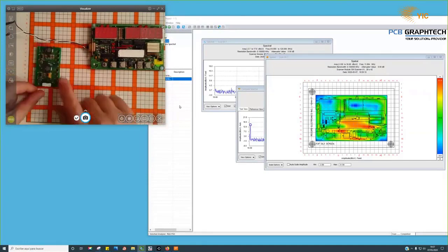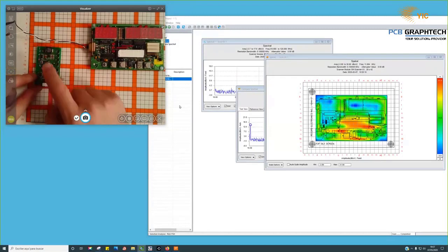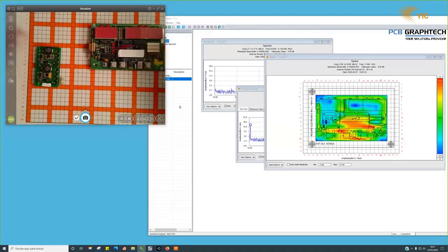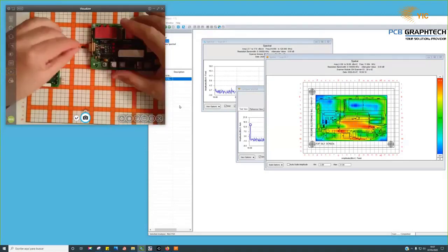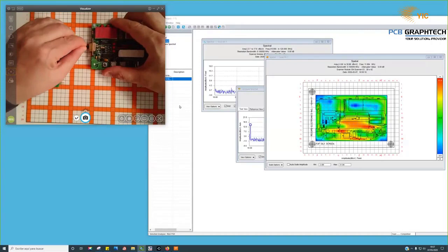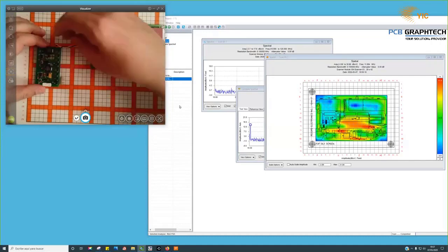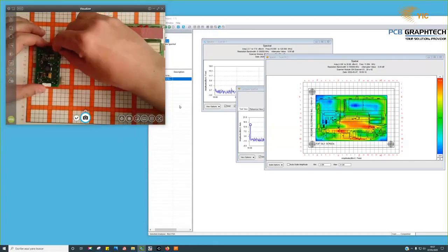I have really here two DC-DC converters. One is a 12 volts and the other is a 5 volts DC-DC converter. I remove from here the 5 volts cable, and let me replace it with a shorter cable, this one. Let me introduce it in the board now. And now I am going to take the output from the buck converter.